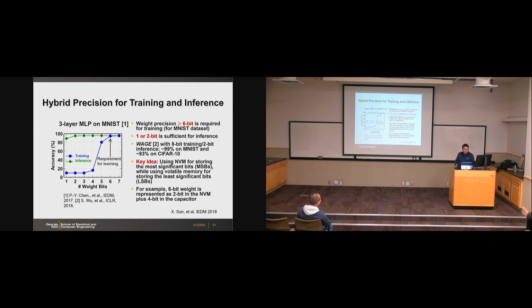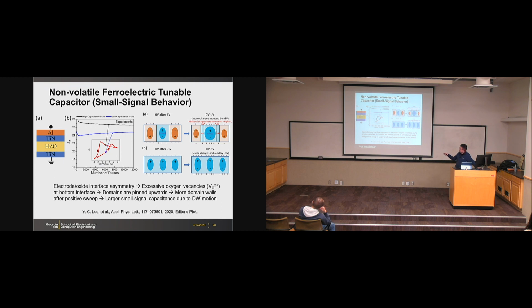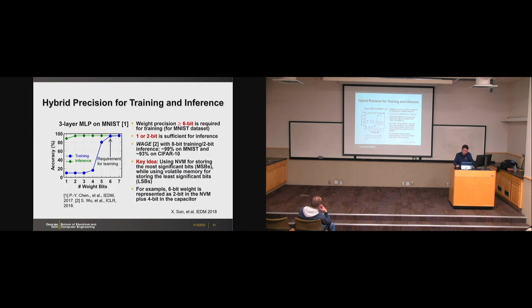So for the capacitor case, it's 2 levels, right? Mm-hmm. So you don't have multi-level. Is it possible? For our first generation, our in-house sample, the on-off ratio is very limited, like 1.2, so we only have 1 bit of data. But recently, in our unpublished work, we have observed more than 30 on-off ratio from a different test structure. So potentially we can do multi-bit with a new design. But in the first design, this one, a very simple stack, yeah, only on and off.